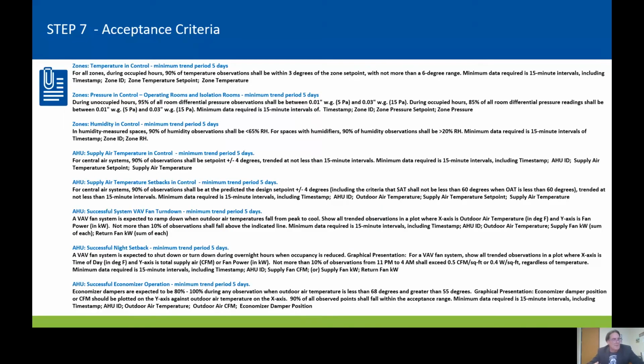So you actually need to put acceptance criteria for everything that you want to be successful into your control specs. Acceptance criteria look something like what you've seen on this page, so you can jot down some notes if you want to. You need to actually state the high and low acceptable values and the acceptable deviation in the data, and you've got to put that in the specs along with all the points that you need to do the validation.